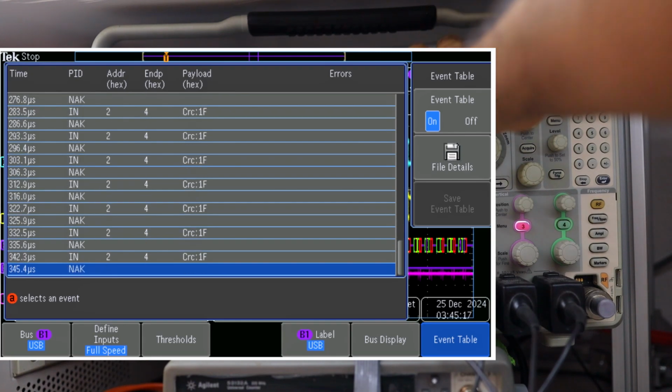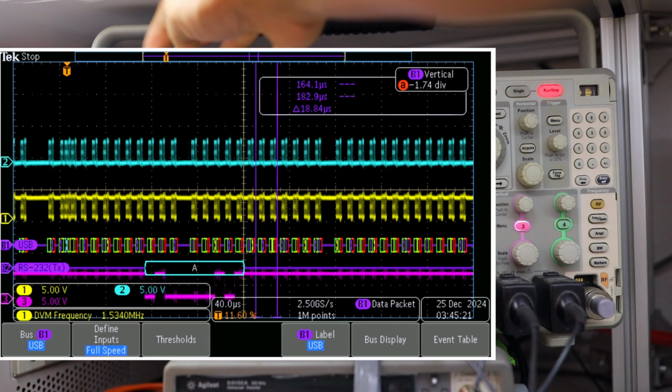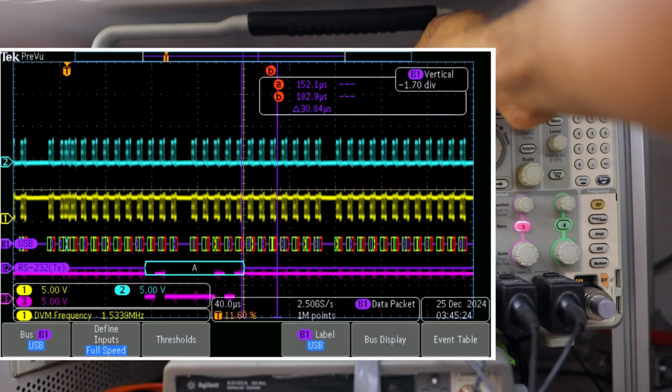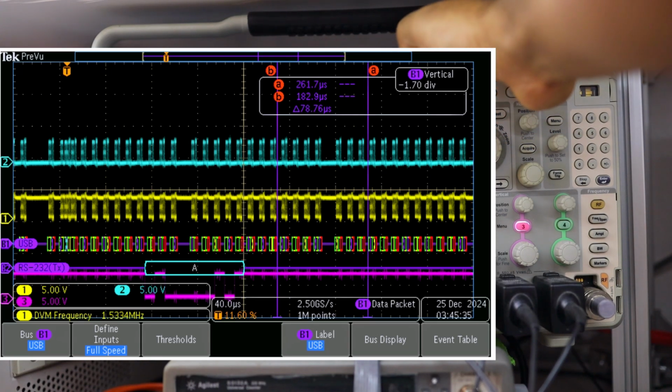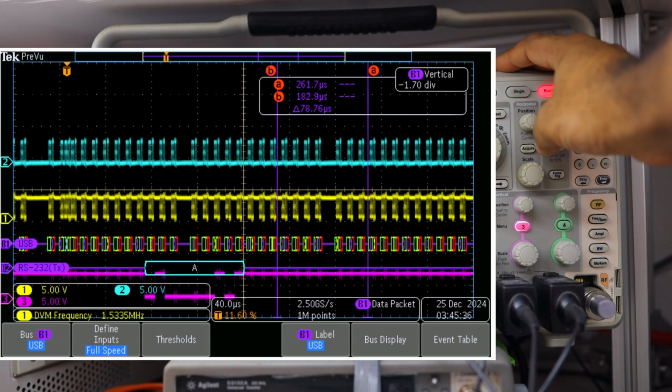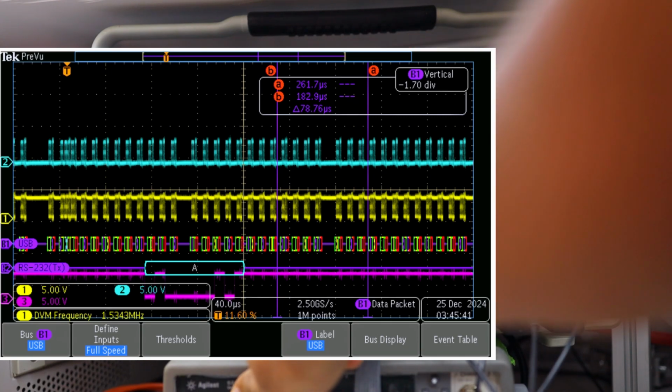No, we do not see it. So we'll do a little bit larger capture this time, because you must understand, once the packet came in over the USB with content A, it got transmitted over UART, and the same thing will be received, and this should be transmitted back because of the loop back connection over UART, the same thing should be sent back over the USB. I'll try to find that packet as well. Okay, so USB is correct.